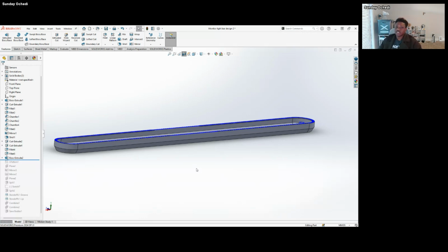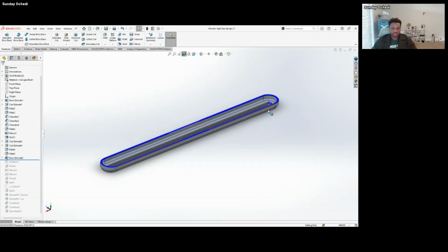And when you consider a manufacturer, yeah, I'm going a little bit off. Most people prefer to use screws because it's way cheaper to do than snaps. Snap fits can be expensive depending on the way you design it, it can be expensive to manufacture. So a lot of people use screws, and I went with screws here.